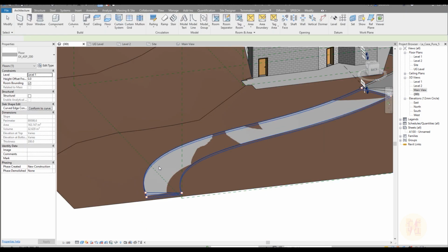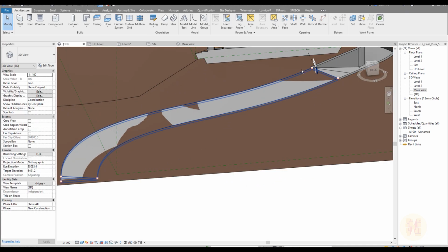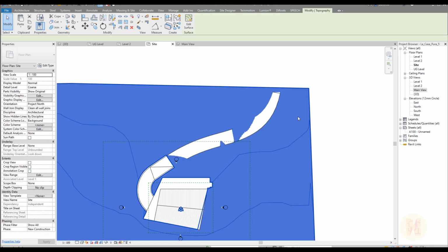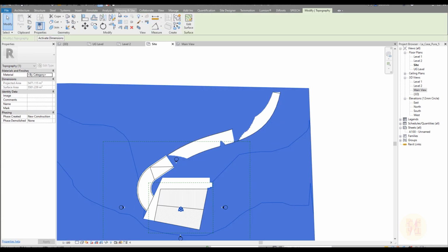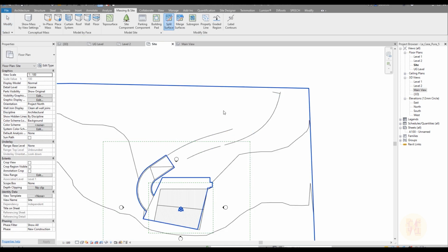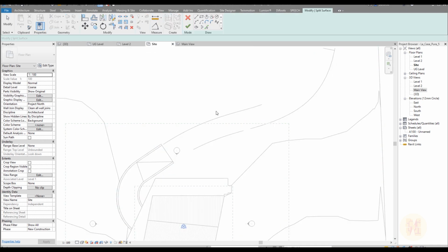And as you can see, our road now lies exactly on our ground. But our ground sometimes covers it. So yes, you should do the same thing. Go to the edit side, and you have two ways to solve it. You can go to the edit side, masking in place, and you can use the subregion. You can use, for example, building pad, and this will be up to you which way you want. We will split it. Let's split it, and now split surface. Yeah, this one.